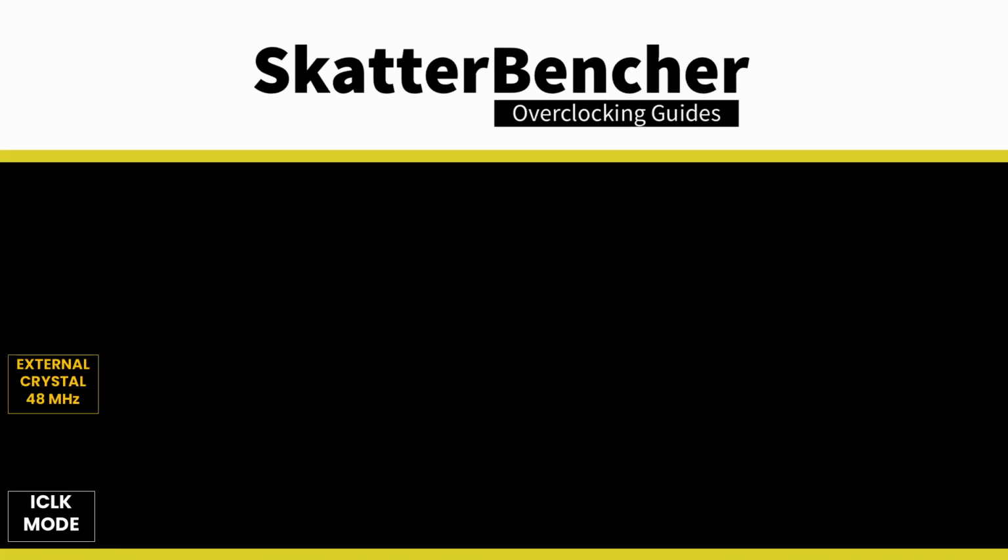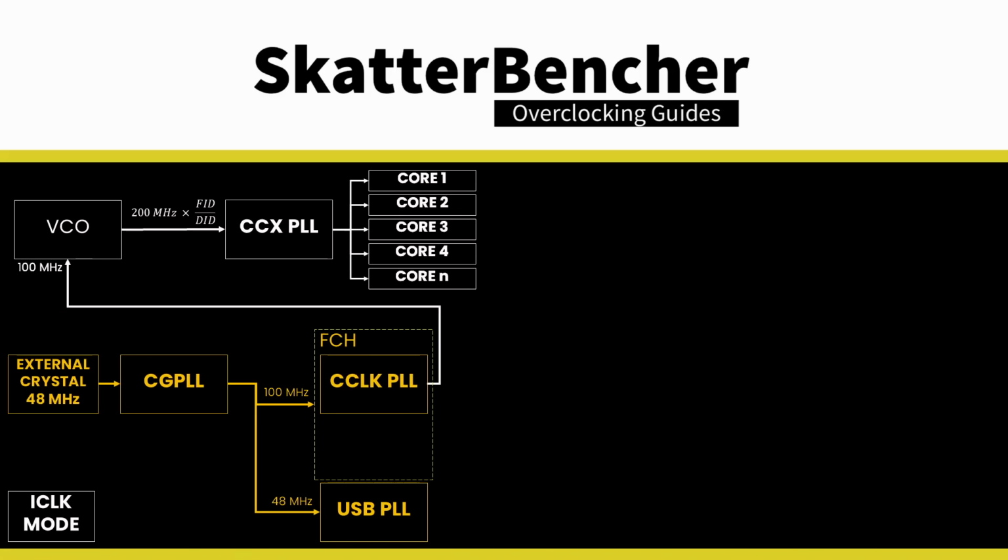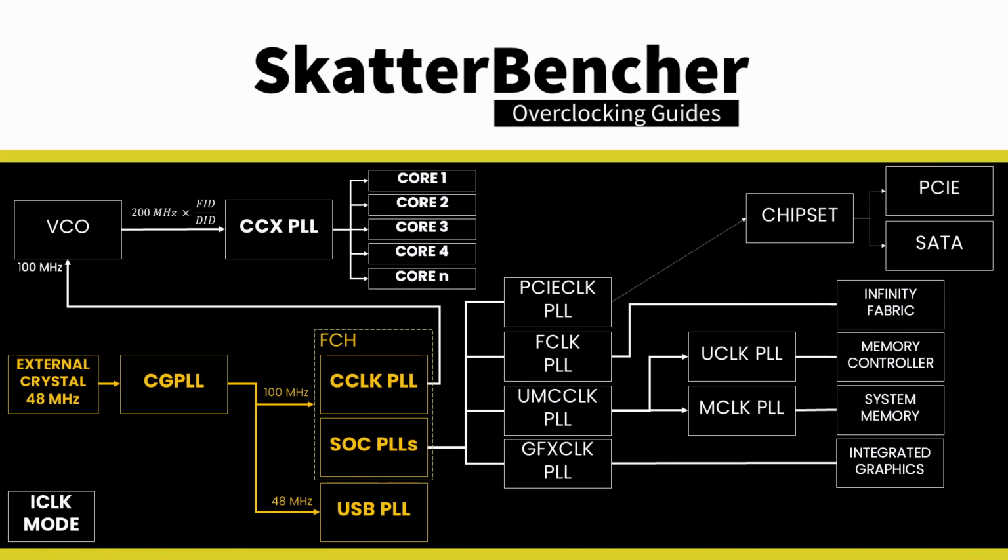The standard Granite Ridge platform has a 48 MHz crystal input to the integrated CGPLL clock generator. The CGPLL then generates a 48 MHz clock for the USB PLL and a 100 MHz reference clock for the FCH, which contains the CCLK PLL for the CPU cores and several SoC PLLs.